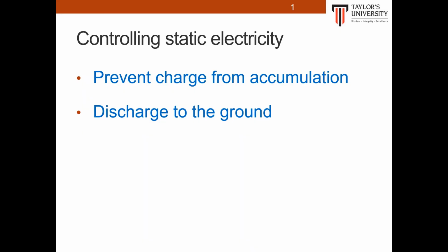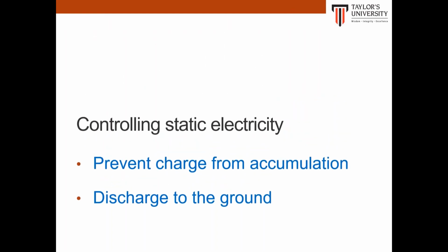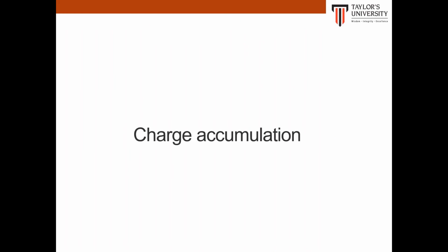There are several ways to control static electricity. One is to prevent charges from accumulating, and the other is, once we have these charge accumulations, to discharge them to the ground. But before that, it is important for us to understand the charge accumulation processes.